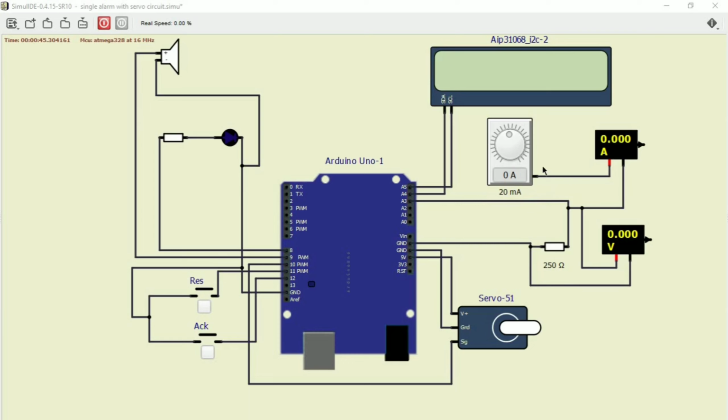This valve will be controlled by a 4 to 20 milliamp signal in the form of a current sensor, and this sensor will simulate the DPT, or the differential pressure transmitter. Besides, this will also give us the monitoring of the water level in the vertical boiler's drum.